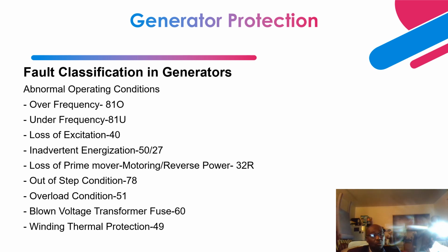So what happens is, if during a major or minor outage an operator inadvertently closes and energizes the breaker in the switchgear, it's going to lead to 3 to 4 per unit of current, if you have a strong grid, and your voltage level will also experience an abnormal condition.